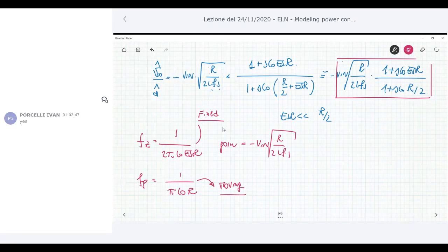Why do we have just 1 pole instead of 2, like, for example, as I said, in the buck CCM? You have to understand that anytime you have a pole in a dynamic system, that pole is related to reactive elements inside that circuit, elements that are able to store energy. For example, inductors store energy into the magnetic field surrounding the inductor, and capacitors into the electric field.